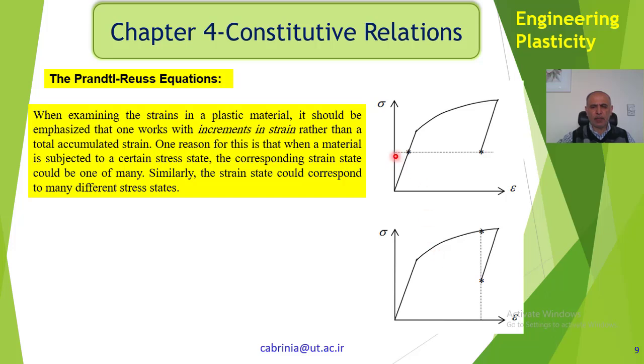In the first figure I have drawn a horizontal line, so you can see that we have two points with one value of stress but two values of strain. Therefore you cannot make a straightforward relationship between sigma and epsilon.